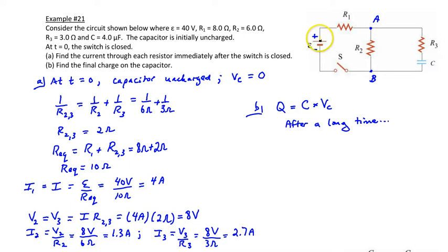Hopefully you'll see that this current that goes through the battery will go through this resistor. When it gets to junction A, none of the current will go through here because the capacitor is fully charged. And so it'll go through B here, our resistor 2, and then continue around through the circuit like this. And there won't be any current through this section over here.